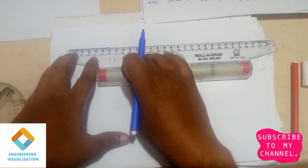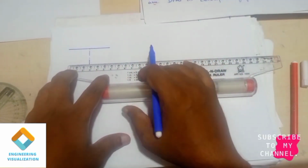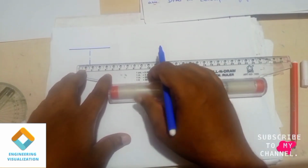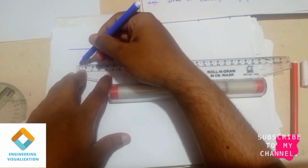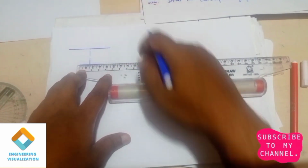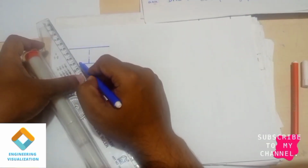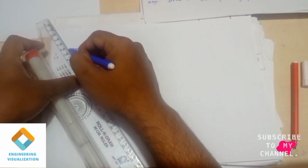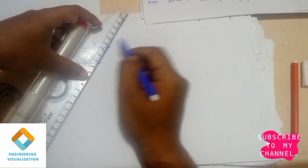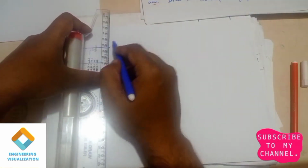This is exactly 60. From the center we have drawn a line. From this center we will be drawing 30, meaning from the center I will consider 15 on both sides. Now we join it. So this is the tapered section of the funnel. Now you can show the dimensions.